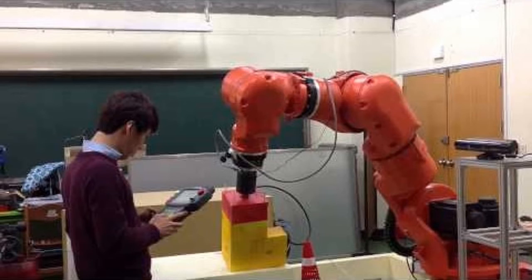So this can be a very time-consuming way to program if there are a lot of steps, but it also can be useful to be right there on site if you need to navigate the robot around any obstacles, or move it to a very specific location that you don't have documented necessarily. A teach pendant can be a really good way to do that.